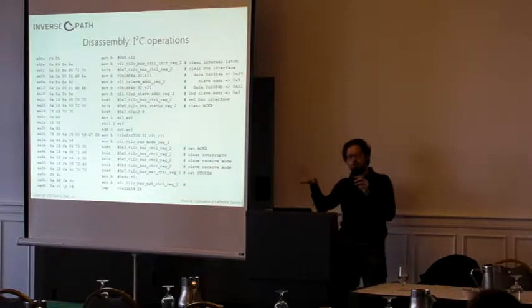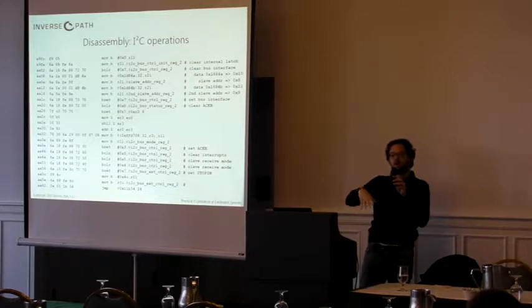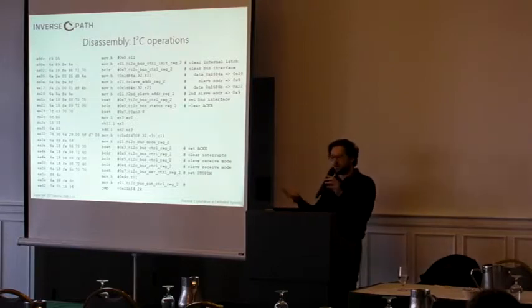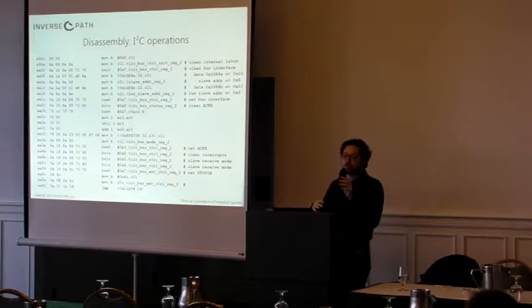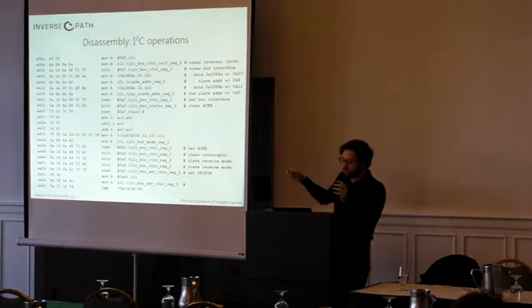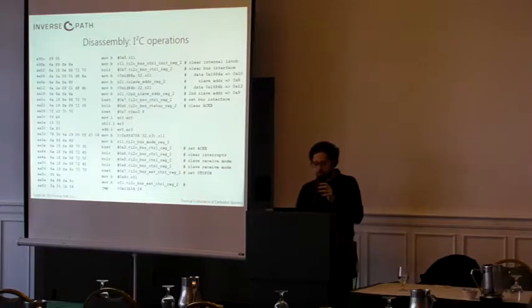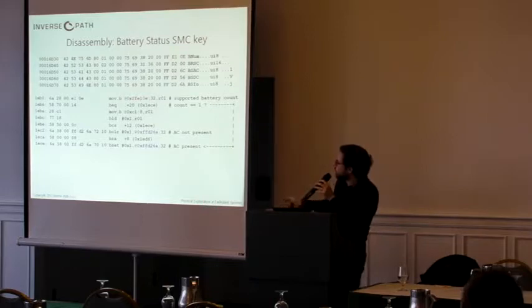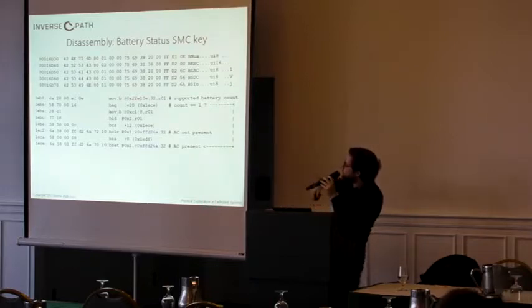So this, for instance, is the code which talks to the battery for managing the battery operation, because the battery, and you might have heard of Charlie Miller's talk about Apple batteries, talks through I2C to the system. And in order to do that, it goes through the SMC. So the SMC can control the battery. And this is one example of a routine which actually responds to the SMC key and gives you an output back.